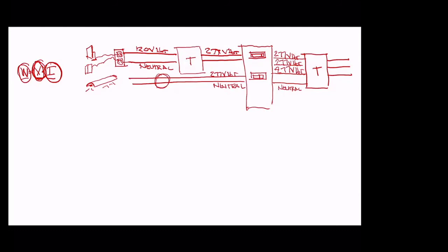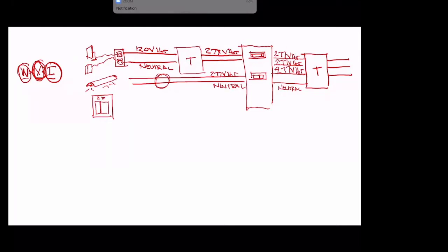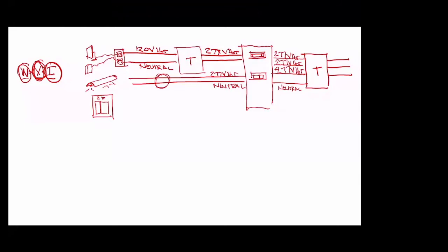Then for the elevator, we need a lot more, and we can't just bring that by having a thicker wire, because then that wire would get hot. If we need a lot of power and we have a normal amount of voltage, then we have to make it up with a bigger wire size, more current, more amperage. And so by doing that, we're risking fire from the wire getting hot.